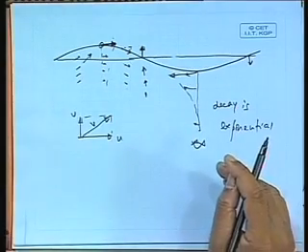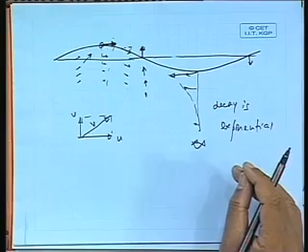Therefore, the thumb rule is that if you take water depth as more than half the wavelength, you can assume the water is calm, no disturbance, because the disturbance factor comes down to less than something like 0.4% or so. So it can be taken to be a steady water wave.